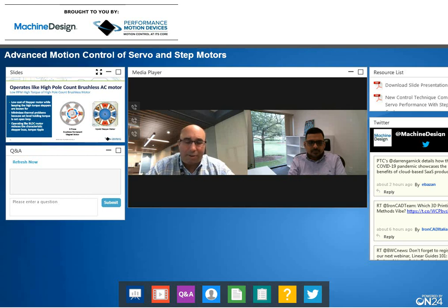Whereas if you move over to the left of that just a little bit and you look at the three-phase permanent magnet motor, really that's what we would consider a four-pole motor. And for a traditional hybrid motor, they run 50 pole pairs. And on a traditional three-phase permanent magnet motor, they're going to be two pole pairs to maybe 4 or 5 pole pairs. It tends to be kind of the range.